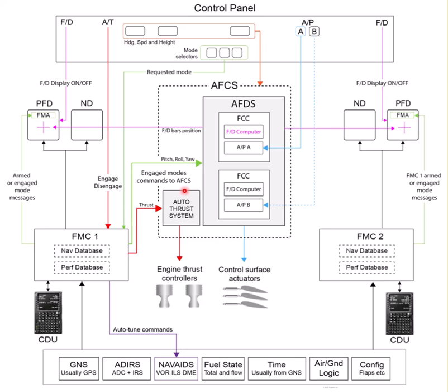Okay, so having pressed the TOGA button on takeoff, I get takeoff thrust, and in the climb it will revert to climb thrust if that's what I'm asking for. So let's say I'm not doing LNAV or VNAV yet, I'm just selecting flight level change. So as I climb out, flight level change will look for the height that I've selected in my height window, and it will also look to see whether that height is above or below me. So if that flight level is above me, obviously I'm climbing out, then it will tell the auto thrust system, oh, we're climbing, so you need to select climb thrust. And that's what will happen.